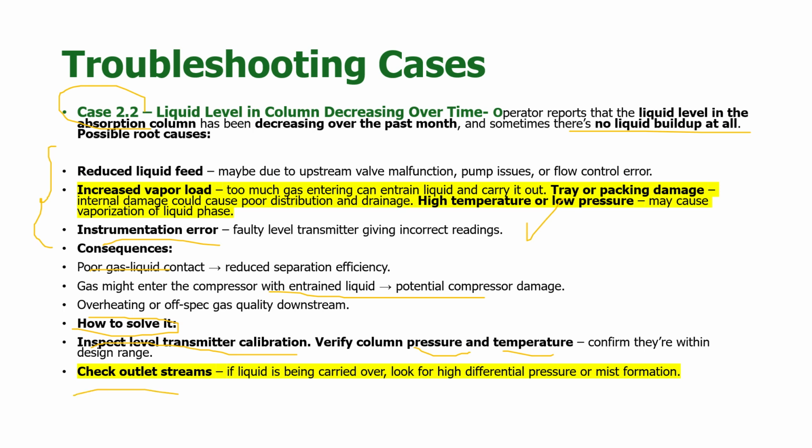Then as a process engineer, you need to be simulating or doing some Excel calculations on the separator sizing to make sure that your outlet streams are correctly aligned and you don't have gas blow-by, gas carry under, or liquid carryover cases.